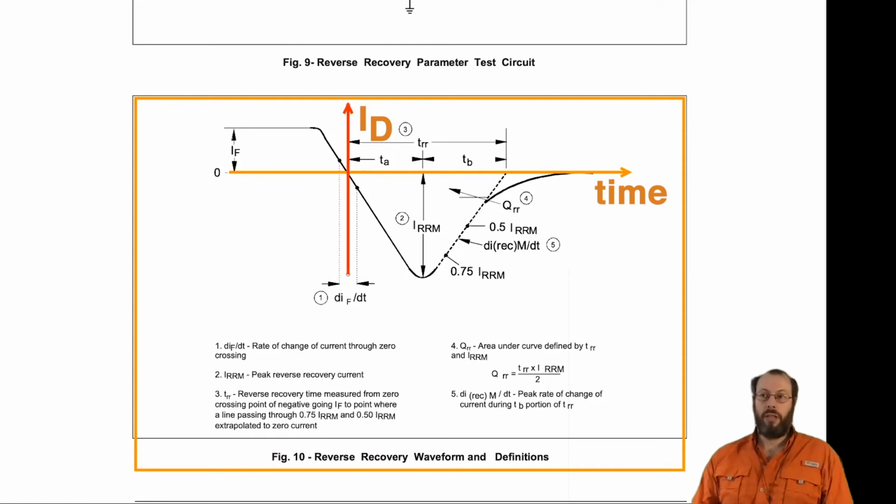We are specifically looking into the switching instant where we had the diode conducting, as in the buck converter example. The diode was conducting all the inductor current, which we've drawn through the red stage. But at some point, we turn off the diode, and the switch in the buck converter takes over the inductor current. That means the diode current is ramping down to 0.